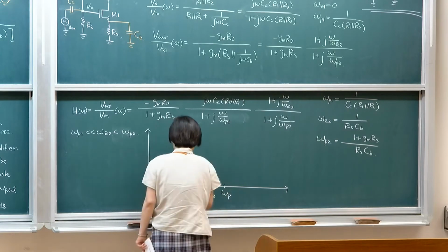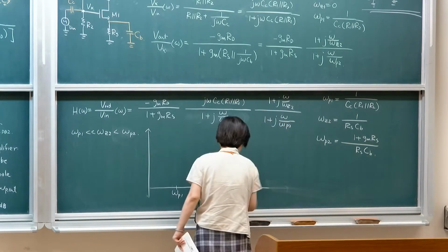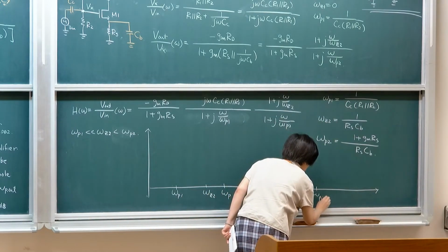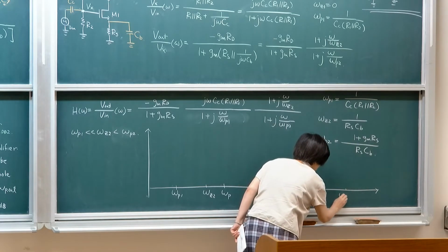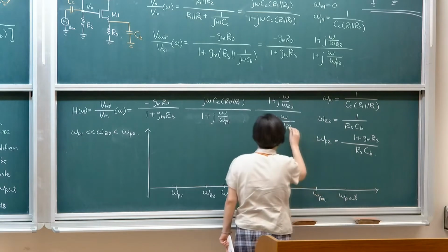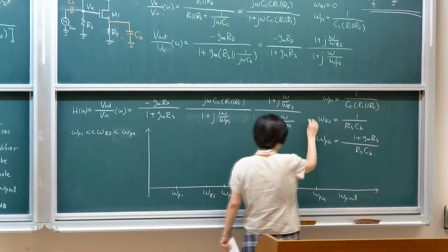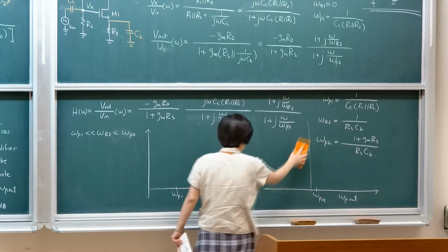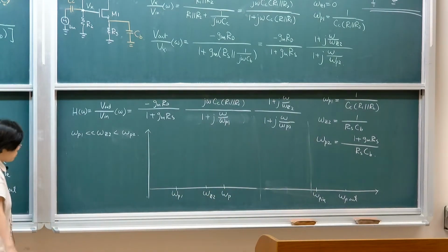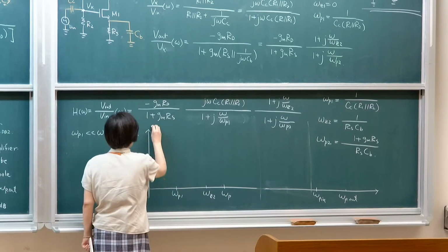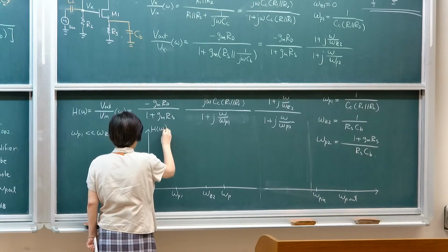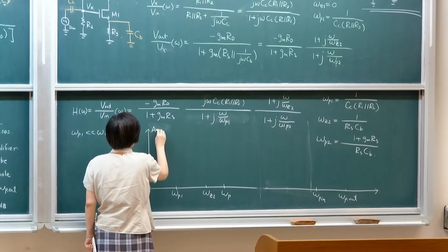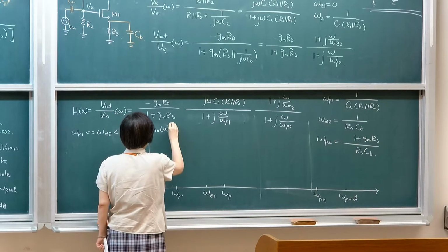And then a very, very long distance away, there will be our omega p in, which is the high frequency component, and then omega p out. Okay? So in a very high regime, these are parasitic dominated, and these are coupling or external capacitance dominated. So let's do the overall Bode plot. The overall voltage gain as a function of frequency, as defined by VL.